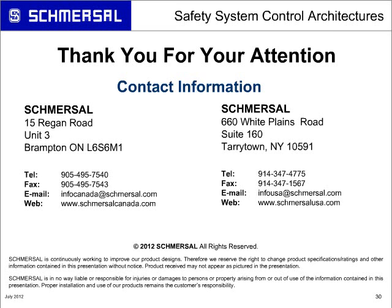How do I assure that a press stops when a guard is interrupted? I think that's a loaded question, and that might be a separate conversation offline. It really comes down to the overall design of the press. Is it a mechanical press? Is it a hydraulic press? Is it a pneumatic press? Is there residual motion? I'll just use an example of a hydraulic press.